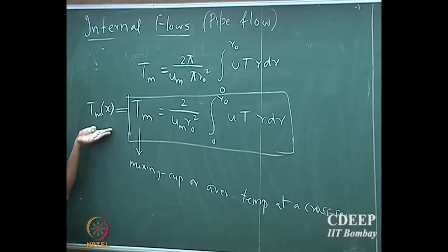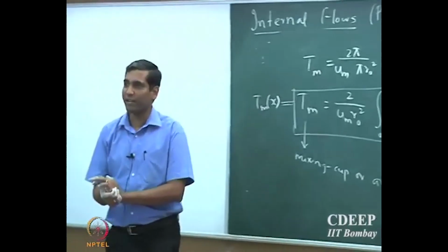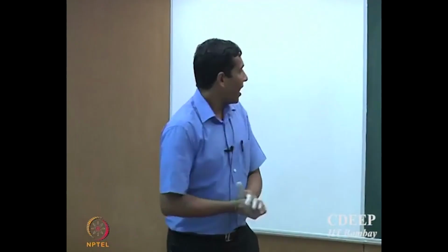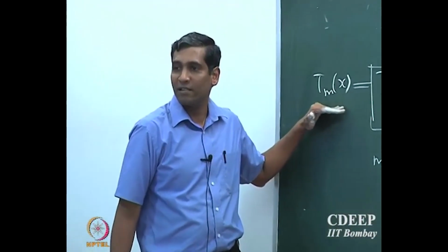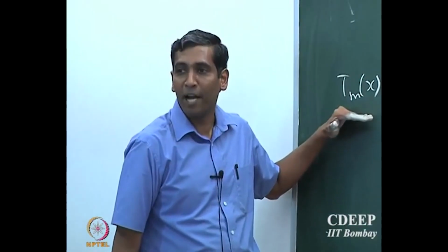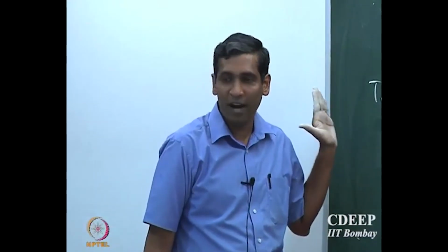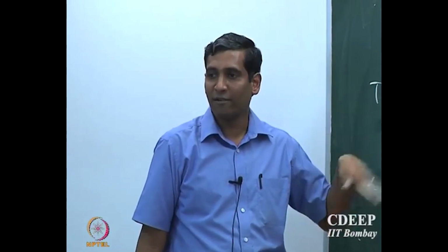position. Okay. So what we will do in the next lecture is, we will start by defining what is called a similar profile. Okay. And that definition we will capitalize on the fact that the mixing cup temperature is also a function of the axial position. We will show that the temperature profiles in the fully developed regime is very similar, and with that we will be able to solve the equations and we will be able to find the heat transport coefficient. Okay.